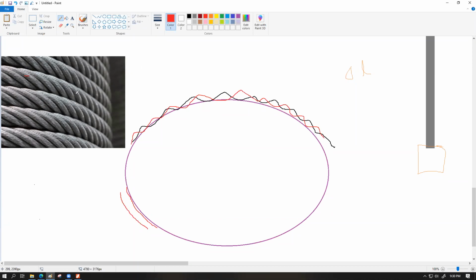Any part of the wire doesn't have to be exclusively under compressive load, it doesn't have to undergo exclusively tensile load. This is the beauty of having this kind of construction, other than having a single thick rod or cylindrical shaped structure, because that would have much less flexibility and will be more prone to break down under bending. So if you want to wind them around rollers or pulleys, this is the shape that is preferable. বুঝতে পারছি?